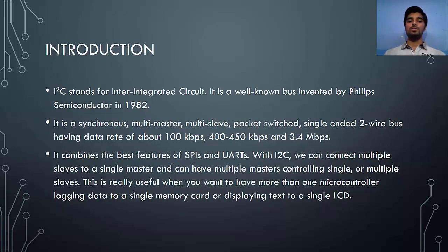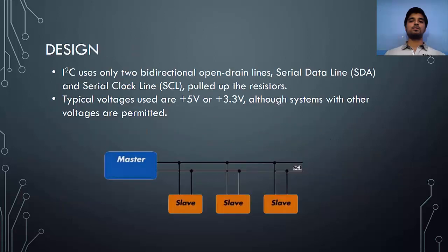It combines the best features of SPI and UARTs. With I2C, we can connect multiple slaves to a single master and can have multi-masters controlling single or multiple slaves. This is really useful when you want to have more than one microcontroller logging data to a single memory card or displaying text to a single LCD.